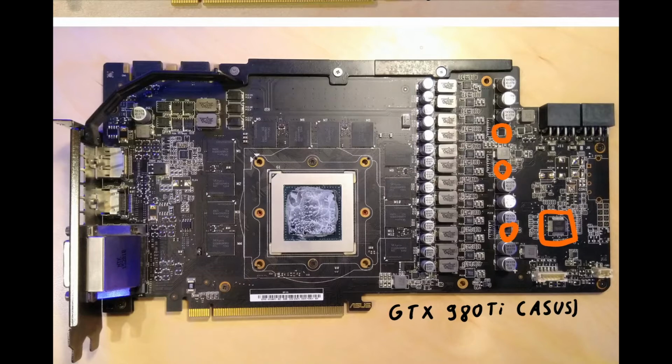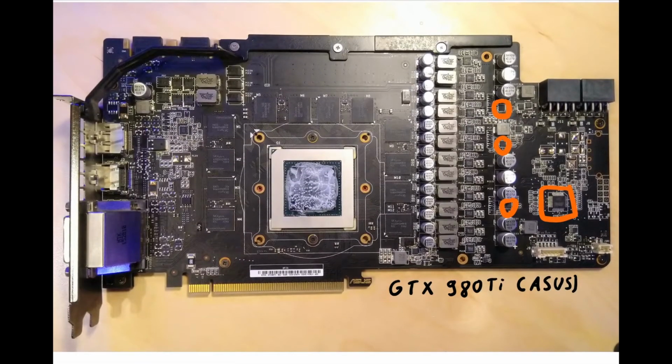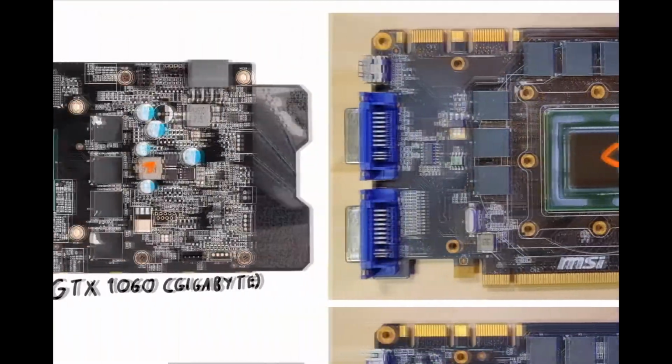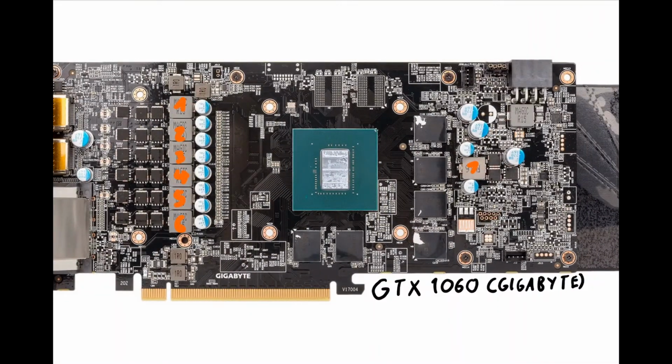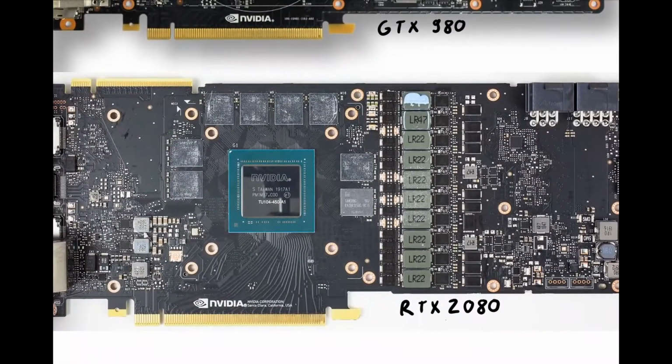So this PWM controller controls the VRM phases, and for each phase it can control, it will send out 1 PWM signal. And if you can find out which PWM controller you are using, you can find datasheets on the internet by putting in the number that's written on it. For example, this over here is a PWM controller looking chip.